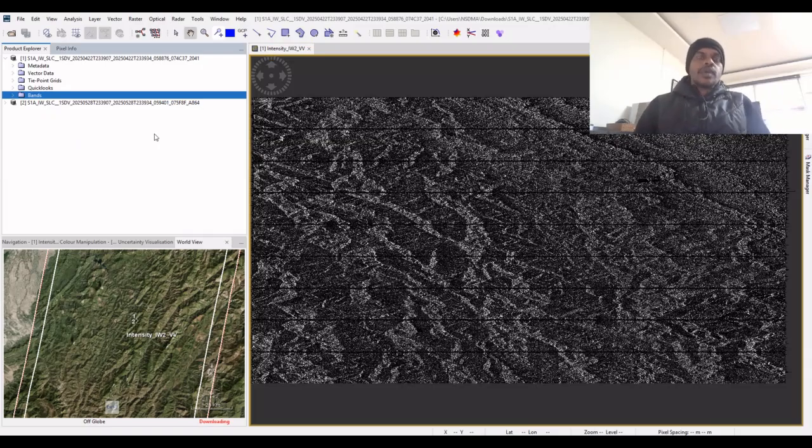Sentinel-1 mainly operates in interferometric wide swath mode, which we simply call IW mode. This IW mode is designed to cover large areas, maintain a good spatial resolution, and also support InSAR applications, particularly landslide monitoring, earthquake deformation or subsidence. But the processing depends. When you are going for time series analysis, you will be using a different set of software like StaMPS or MintPy, and for DInSAR you will be taking only two images like that.